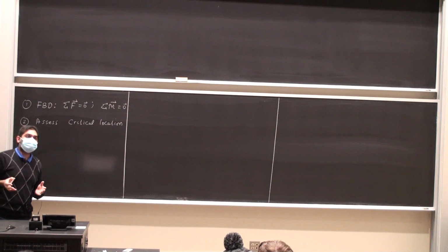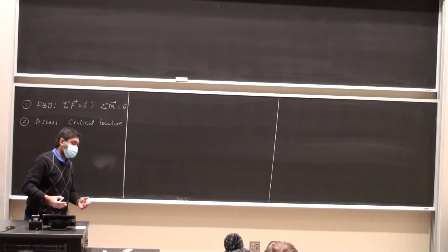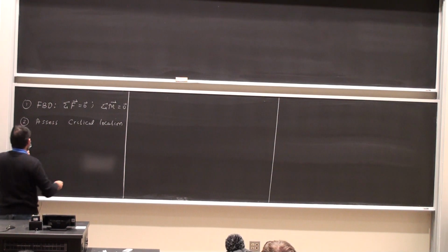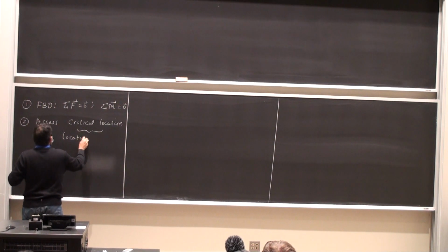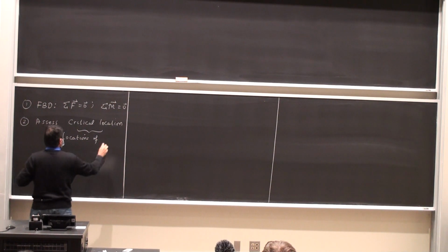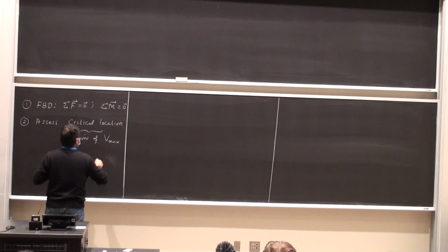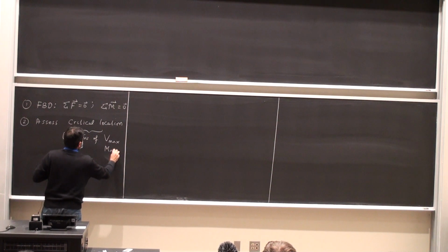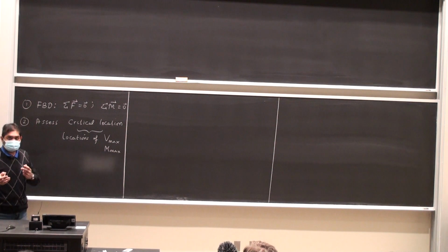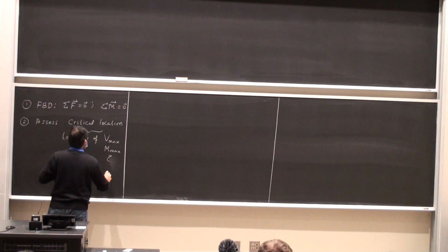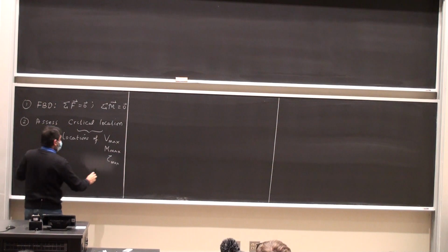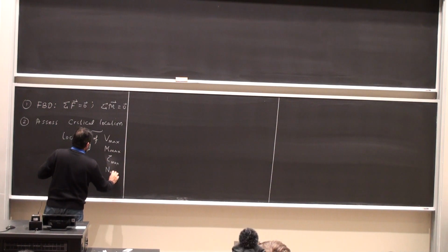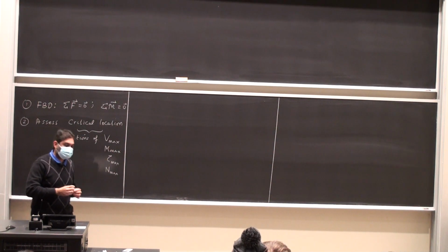The location where the internal forces and moments, or the internal torques, if you have a torsional load, these are the largest. Locations of Vmax, Mmax, T max, all of these are internal loadings, even the normal forces, and N max. I should say T max, not tau max, sorry.